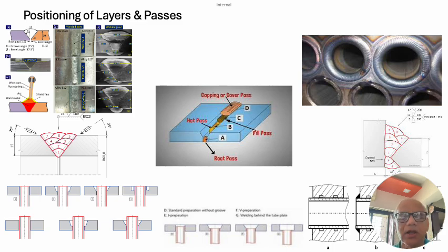If the dilution is less than 10%, it will not create much of an impact, but if the dilution levels are higher, then it will have an impact on every layer, and that is where we need to ensure that we position these layers very well from the metallurgical point of view and also from the non-destructive testing point of view, because based on this positioning of these layers we will have the resultant gap, and we will see that in our next slide.